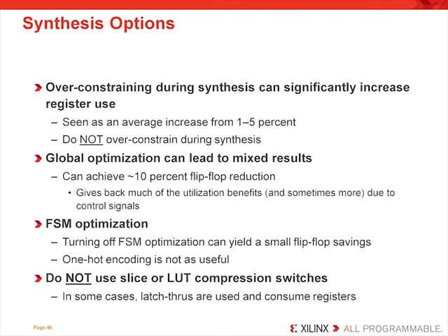I would recommend that you synthesize your finite state machine yourself by trying binary, one-hot encoding, and gray encoding and experimenting between. Then compare results and see which one you like best. It also is important to determine whether your finite state machine is part of a timing critical path, and often they are. If so, you may have little choice but to use one-hot encoding. But be an engineer and evaluate your encoding yourself. Note that over time, this is something synthesis tools will learn from and improve upon.